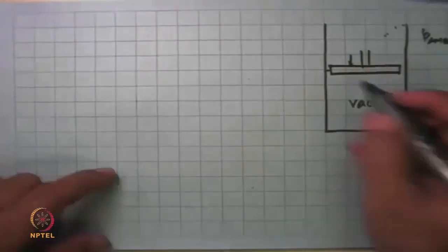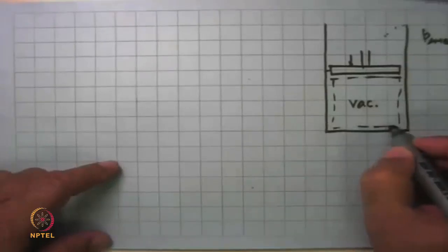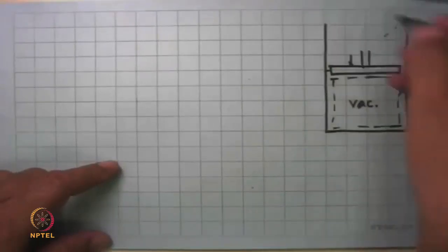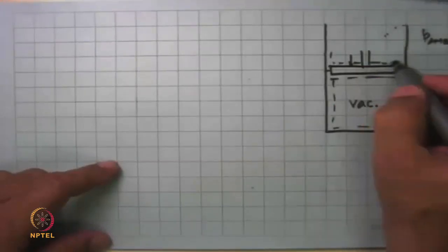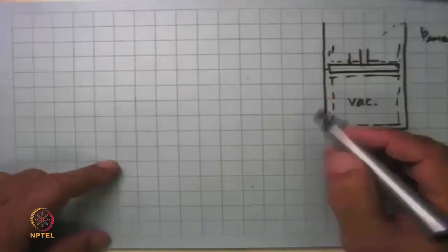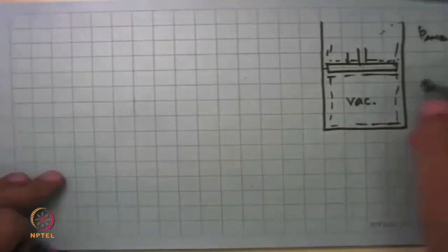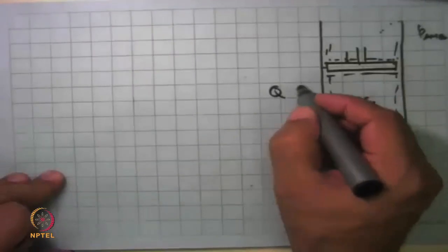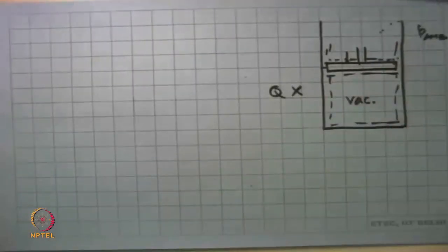We didn't have a process because we did not have a substance over here. The only thing we can look at is what happens to the surroundings or the work done on the piston as it moves, and see what it is that the surroundings experienced. But vacuum, there is nothing, there cannot be any heat transfer to it, and in this case, as we have seen, there is no work associated with it. So there is nothing that will happen with vacuum.